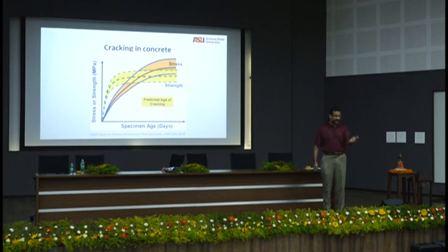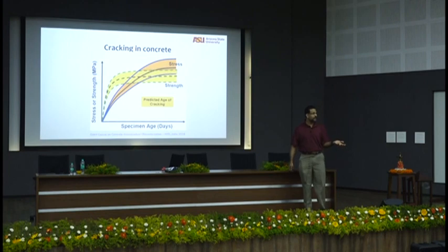And then what are joints? Basically predefined cracks. You're telling the concrete, I don't want you to crack anywhere here, just relax your stresses here, right? Cracks are nothing, joints are nothing but predefined cracks.